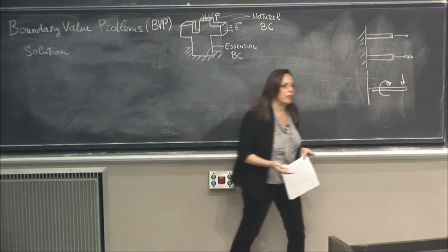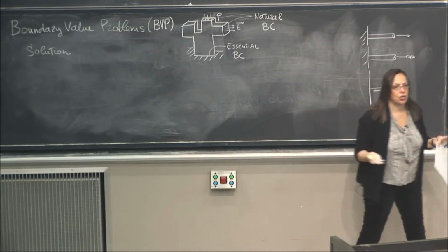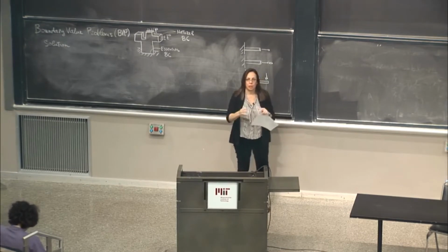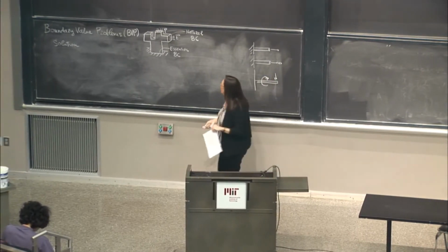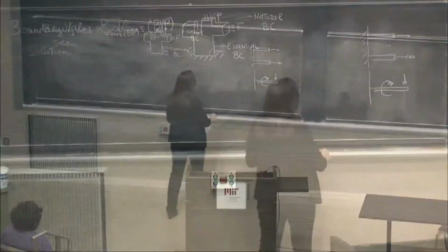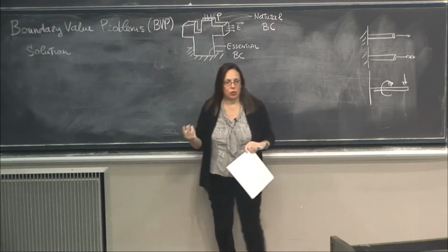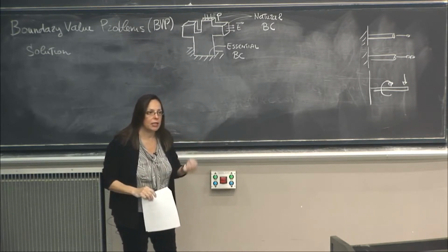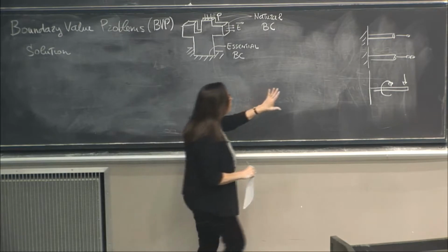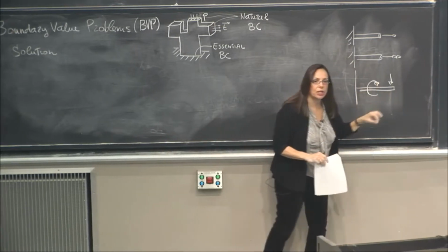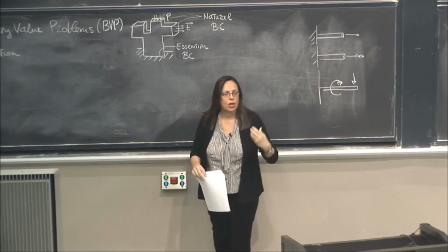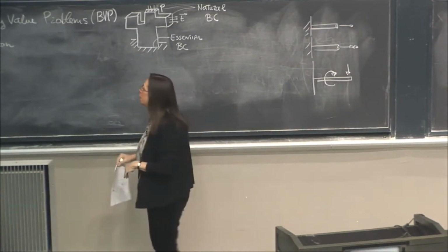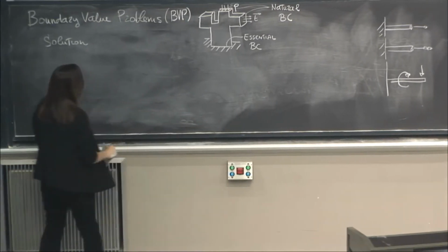And in general, we have been dealing with what we call slender structures, that is, structures in which the cross-sectional dimensions are smaller than the length of the structure. And by applying equilibrium and compatibility and constitutive relationship, we have been able to get an idea of how to predict the behavior of the structure in terms of the deformation of the structure, the stresses inside the structure, how to make sure that the stresses do not exceed some design limits, and so on.